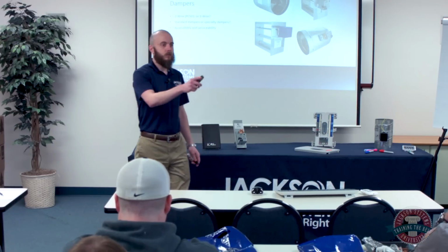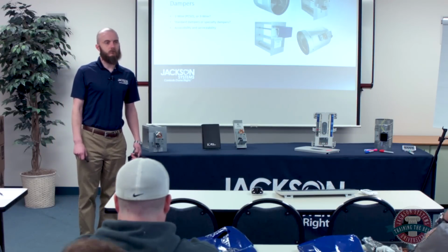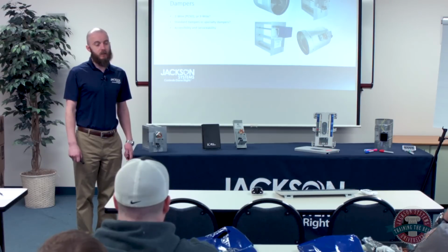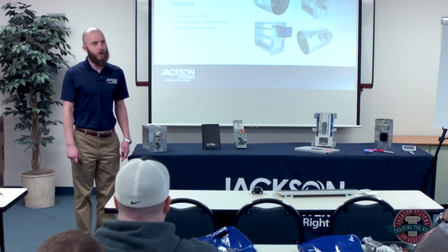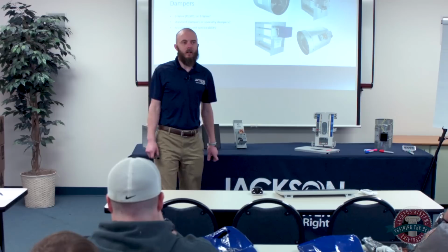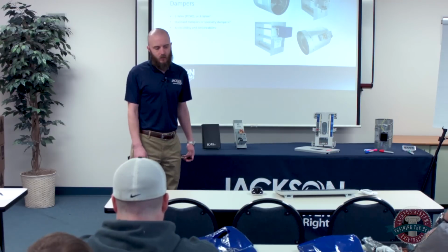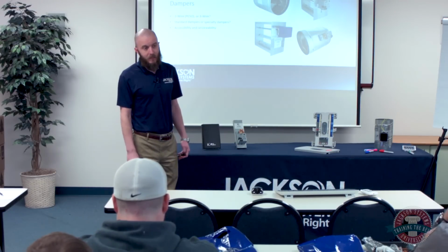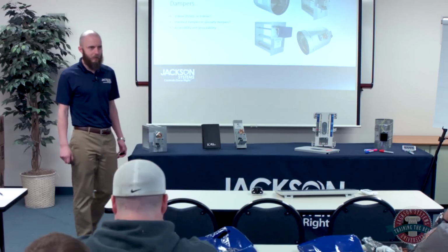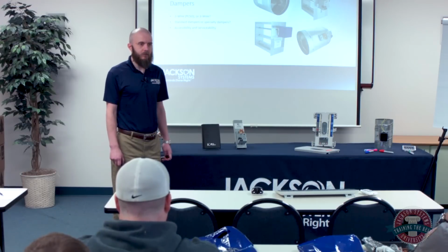Okay, we have a question from Frank. He would like to know if you know of any fire rated dampers that can also work in zoning. Not that I know of. Typically, fire dampers are a specialized area. We don't really get involved in fire dampers, and you would not probably want to mix and match fire dampers and zone dampers. I don't know of any that are recommended for use like that. I'd be surprised if there are, just because of the way fire dampers operate, but it's possible. Typically, those are going to be very separate functions.